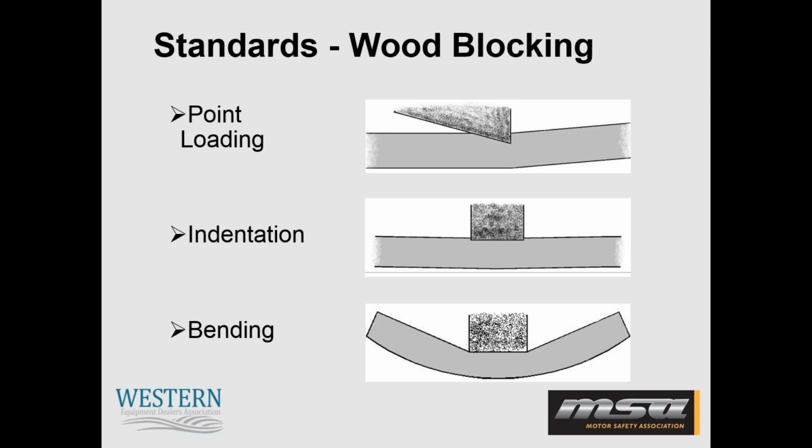And no matter any type of situation, when you are blocking, as you apply the load to your blocking, you want to do it quite slowly. And as you're doing it, be sure to listen for the warning signs that I was telling you about and signs of failure. So we are being aware of the situations where we can see the cracking or splintering or hear the creaking sounds. And people who have used blocks on a regular basis, they've said to me that a wood block will talk if you take the time to listen.